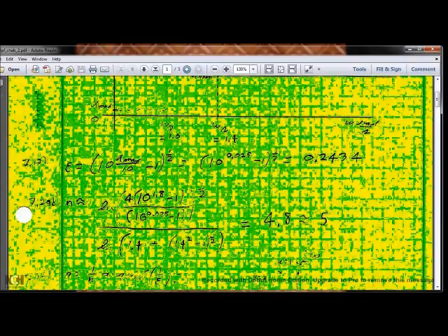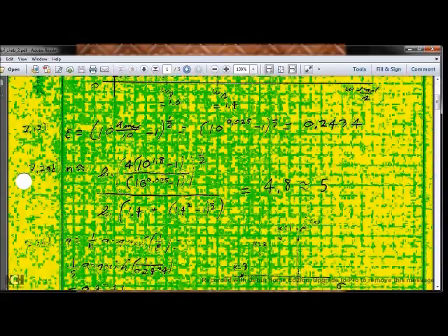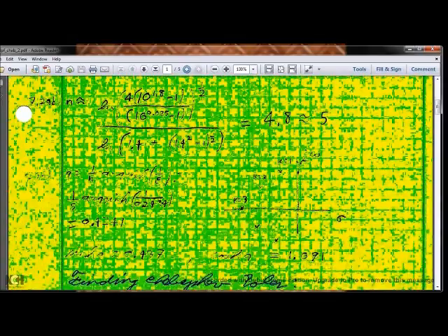Epsilon is the parameter we just talked about. It's 10 to the alpha max over 10, minus 1, to the 1/2. We calculate epsilon. And the order of the filter is the logarithm of 4 times 10 to the alpha min over 10 minus 1, over 10 to the alpha max over 10 minus 1, to the 1/2, over the logarithm of omega s plus omega s squared minus 1 to the 1/2. We get 4.8 and round that up to 5, of course.